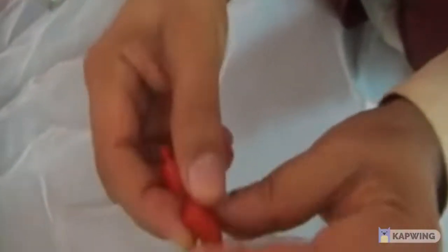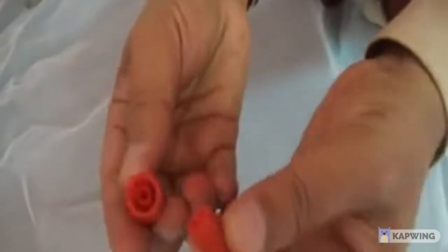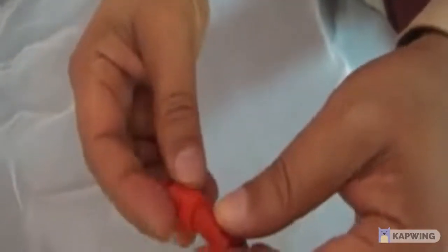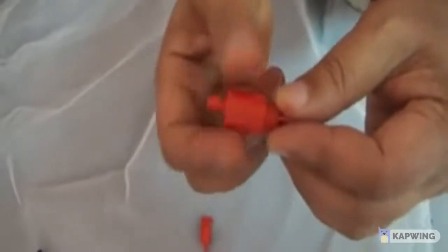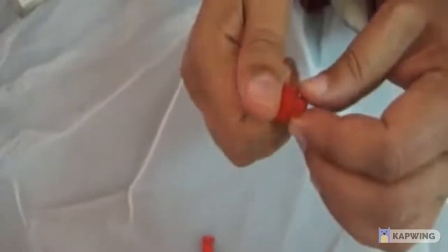So you can see here these 2 components, when we are keeping it out, this is fully open. Now if I start closing it, the opening starts reducing, and then slowly you will find that. So from this dripper I can get discharge from 0 liter per hour, or no flow, to as high as more than 50 to 60 liter per hour that we have monitored.